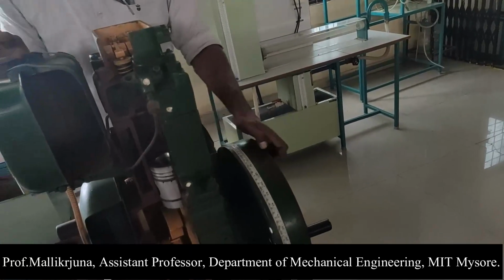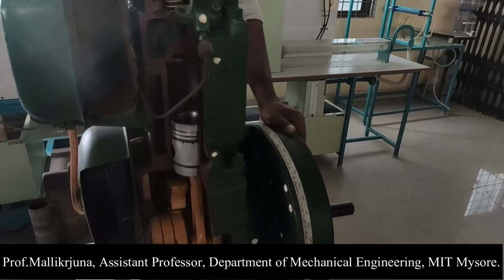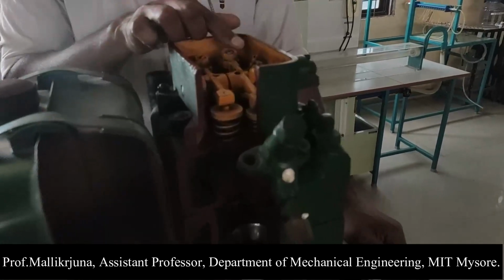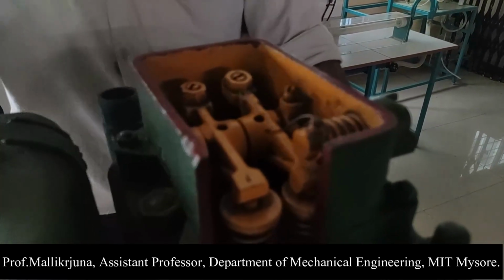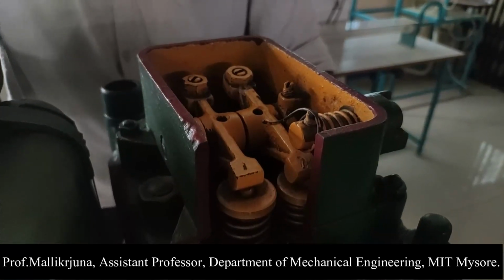Now the piston is coming upwards from the BDC. Exhaust valve is opening still. Still the exhaust valve is having a movement over here. Exhaust valve has not closed yet. Now I am performing an exhaust stroke because the piston is moving in an upward direction.